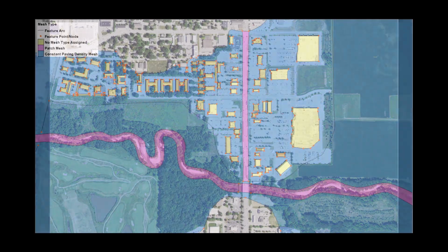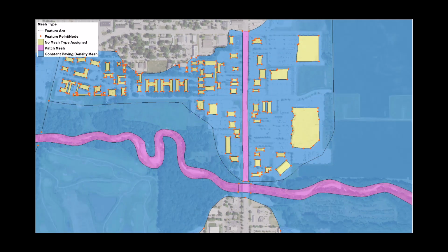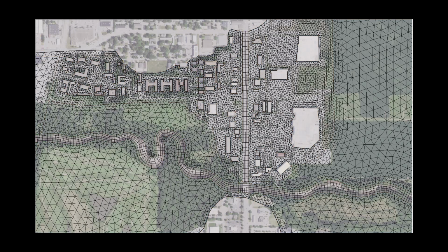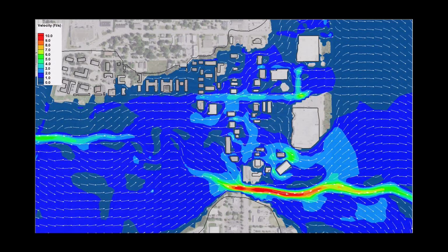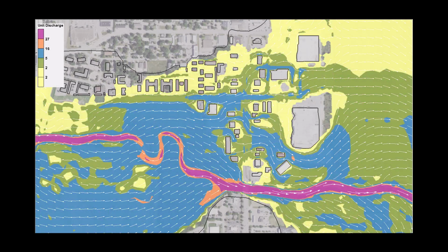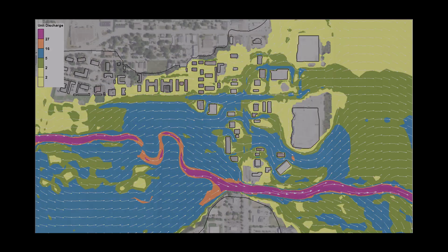This more detailed approach requires more time to develop appropriate mesh geometry and results in a larger, less efficient model. However, this approach provides the most detailed representation of hydraulics around buildings and is the best approach for projects requiring insight into detailed hydraulics at specific urban locations.